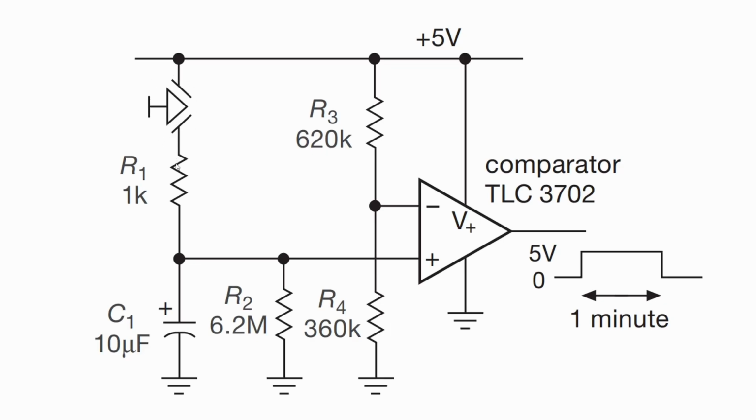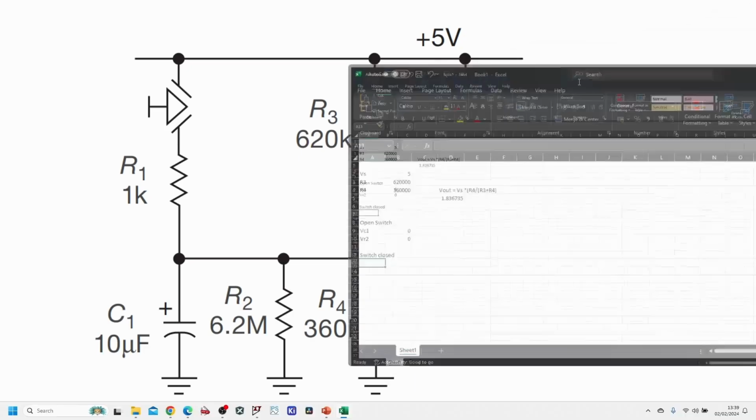So if you imagine a very high rise rate pulse going through this node, at that time, the reactance of the capacitor is going to be very low. There's going to be a high amount of current flowing through this capacitor, and that will cause this capacitor to start charging. So initially, the voltage across this node when the switch is pressed is going to be 0, but will rise rapidly to a voltage that is formed by the potential divider of R1 and R2. So let's calculate what that final voltage is going to be and then simulate the circuit.